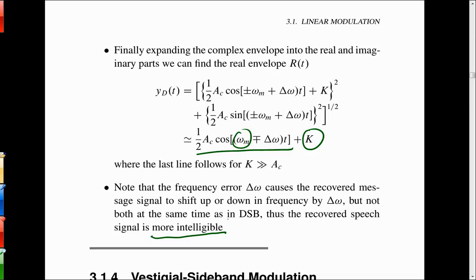Why would you use double sideband type stuff? Why would you use it? Because it's simpler. Single sideband requires more hardware in the receiver. And I didn't mention this fact: the fact that you're sending two sidebands, it takes up twice as much spectrum, but it makes the signal more robust in a noisy environment. We're more susceptible to interference when we have single sideband just because we're only occupying half as much bandwidth. We don't have redundancy or extra protection.